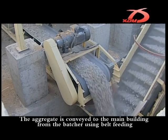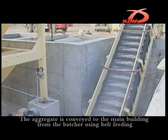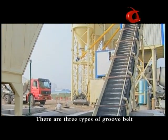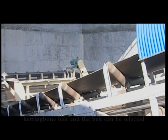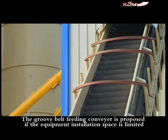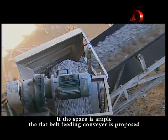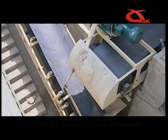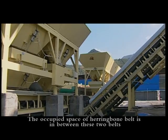Conveyor belt. The aggregate is conveyed from the batcher to the main building using a belt feeding system. There are 3 choices of belts available: groove belt, herringbone belt, and flat belt. The groove belt feeding conveyor is recommended if the installation space is small. If the space available is large, the flat belt feeding conveyor is recommended. The herringbone belt is the best choice for medium-sized areas.